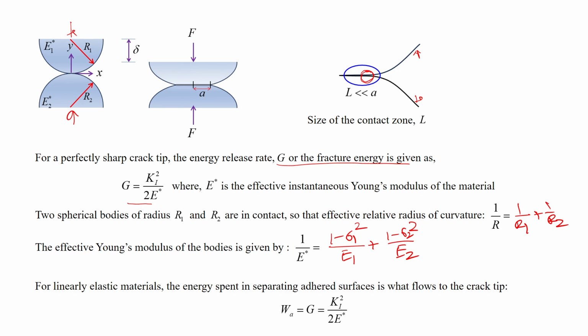And so, for this kind of material the work of adhesion can be directly equated to the fracture energy, and that is Ki square by 2 E star. In essence, there is no dissipation here.